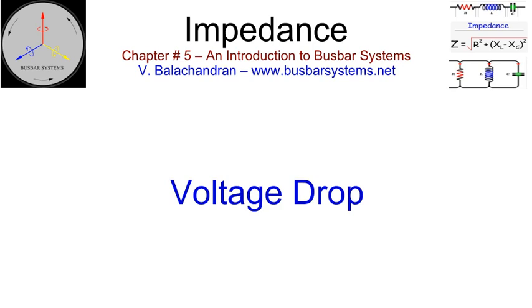In a high current busbar system, the voltage drop is associated with significant power loss in the connections as well. In the arc furnace, the voltage drop will have a considerable impact on the performance of the furnace. In metal extraction plants, the voltage drop in the connections will significantly contribute to the overall cost. In low voltage distribution networks, a voltage drop will result in motors drawing more current and consequently more copper loss, resulting in their running below their optimum efficiency. Some regulations limit the maximum voltage drop in a low voltage network. In the medium and high voltage busbar systems, the voltage drop is insignificant.